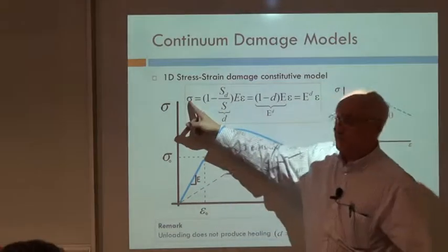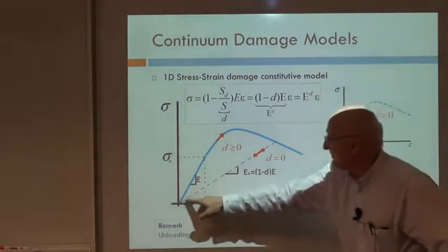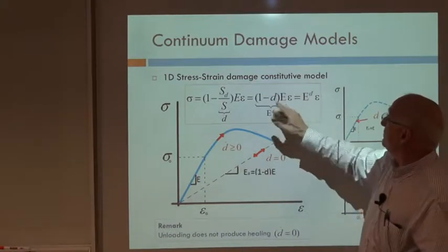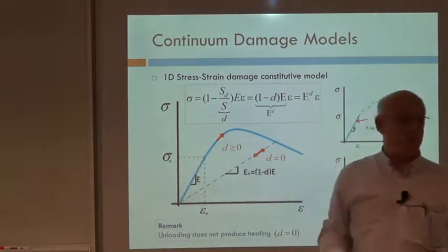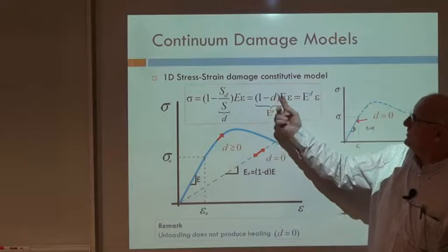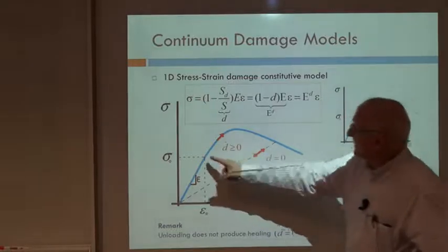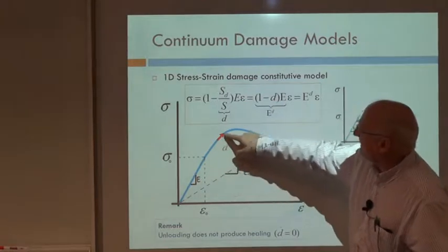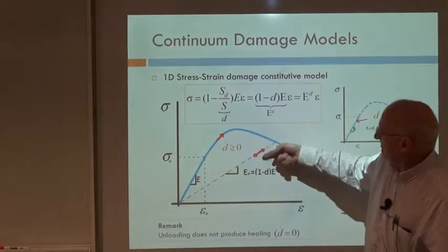So the total stresses and the total strains are related through a varying secant modulus, which is evolving from an initial value, when d is equal to 0 at the very low values of the strains, which we call the elastic regime. It starts from the Young modulus, the elastic modulus of the material, but beyond a certain threshold, it starts degrading following a certain law, this secant modulus being smaller and smaller and smaller.